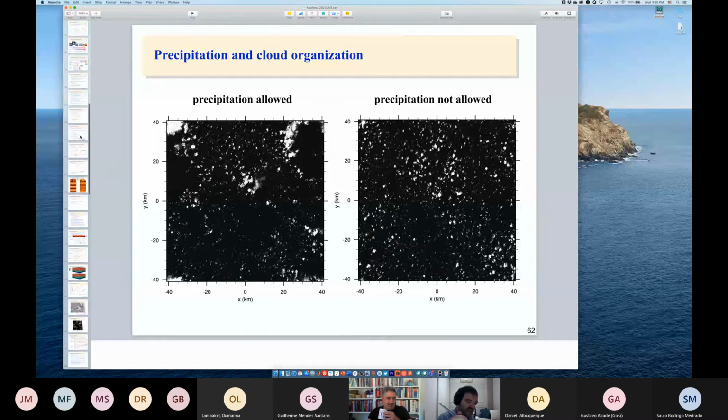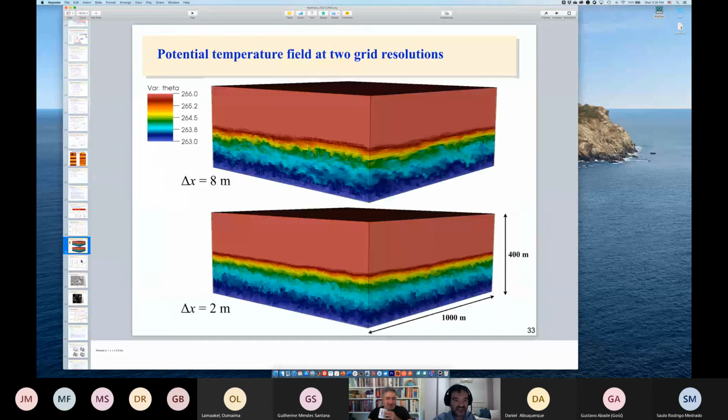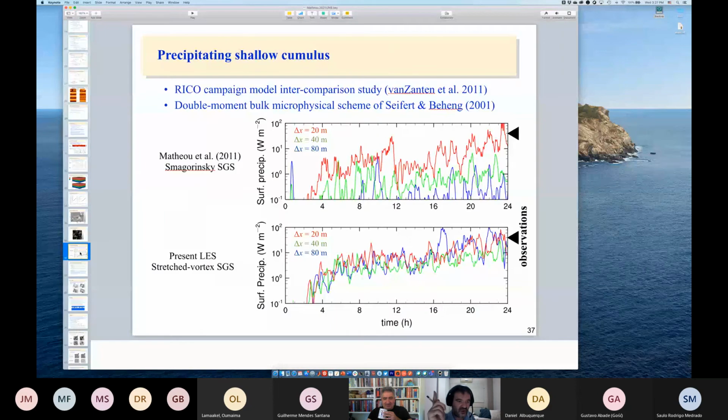Also, when you showed the other presentation, where you showed the grid convergence for different delta x, 2, 6, and 8, I think, then on the following slide you showed results for delta x equals 80. So that's a massive jump in your delta x. Do you still expect to have converged results at that delta x? Isn't the truncation error already something very important? Okay, this is a good question.